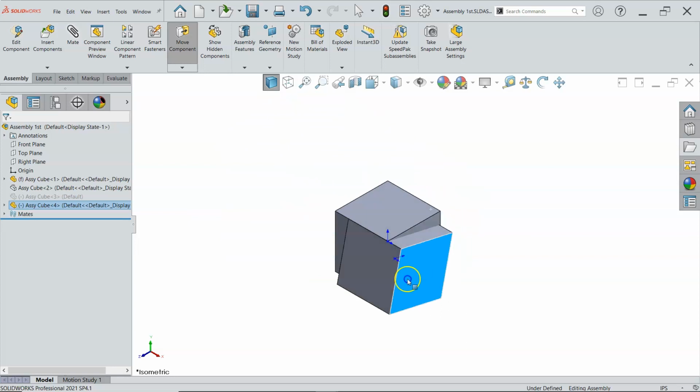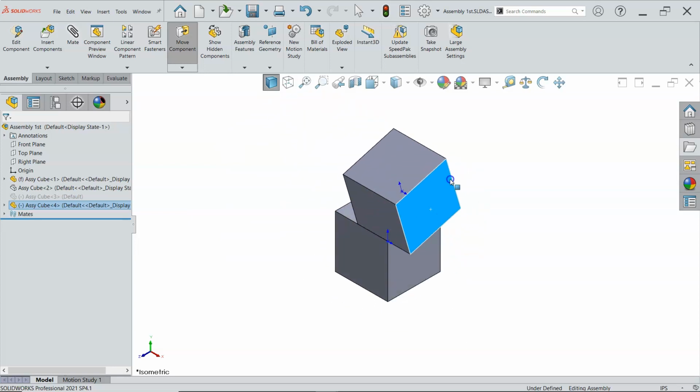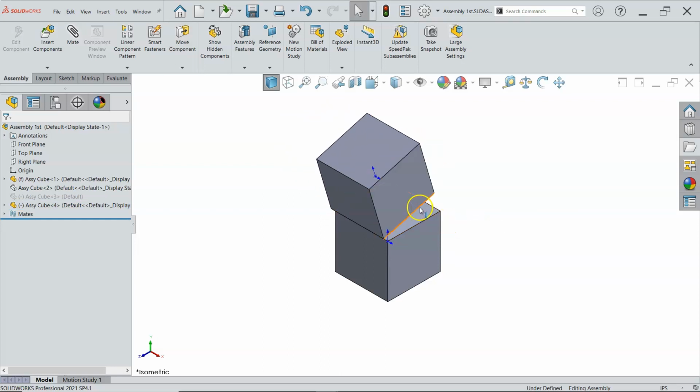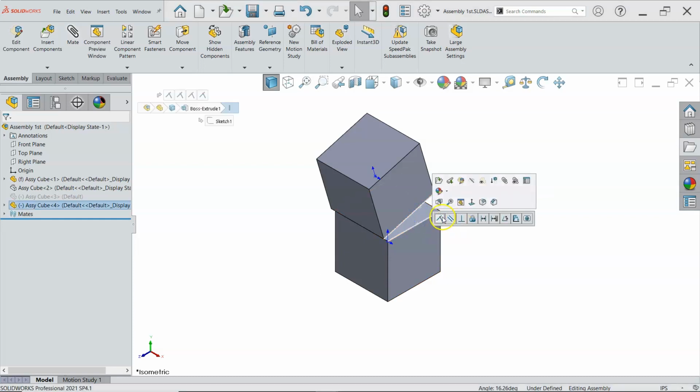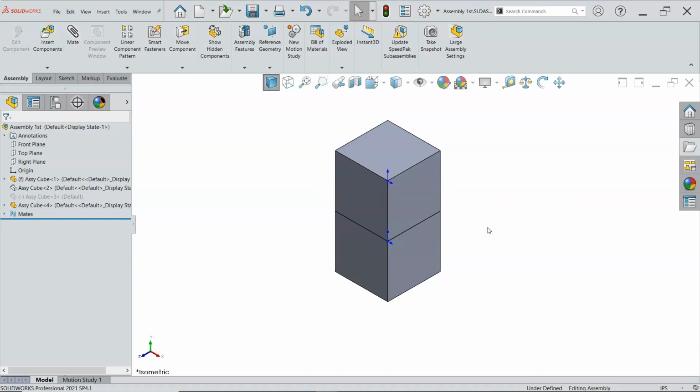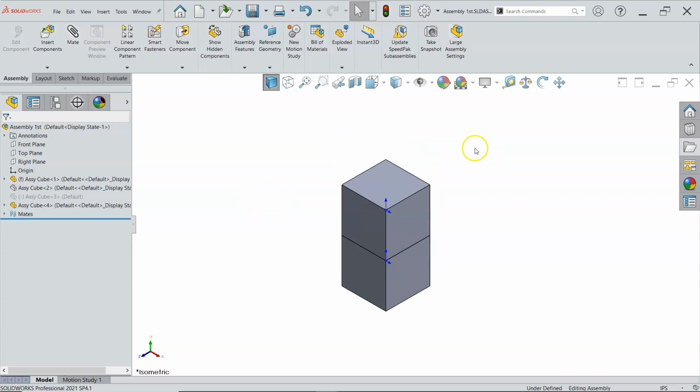And if I'm trying to make an angle or do something along those lines, then that's going to be a desirable result. If I come over to another edge, and make those coincident, well, that will allow this to go fully defined. So I got the same basic result in two mates. That's still not going to be my preference. If I have a problem and I have to diagnose this, I'm more comfortable working with the faces than dealing with the edges.